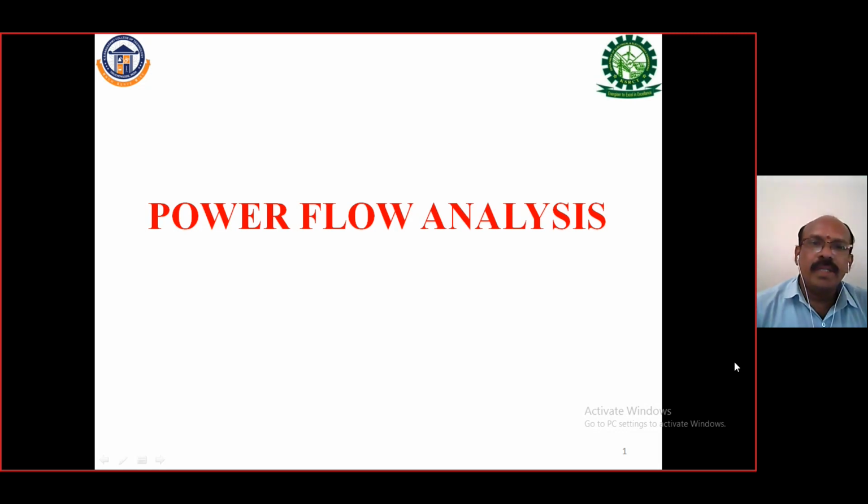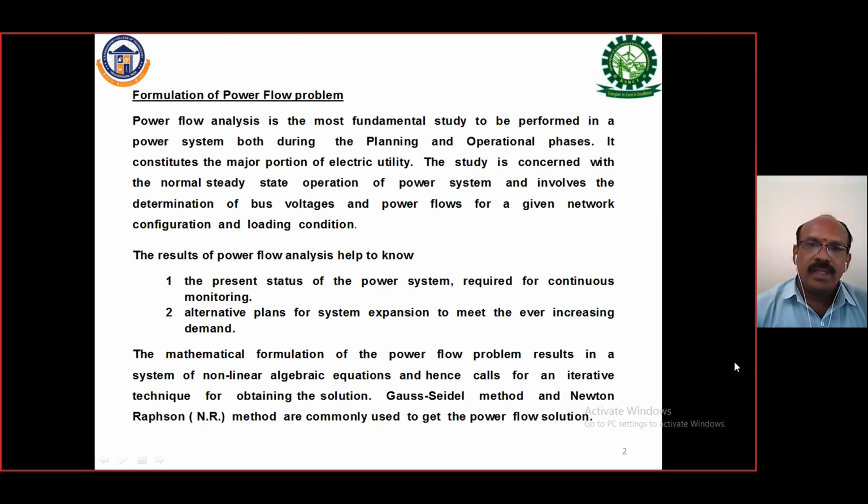Today I am going to take the class Power Flow Analysis. Actually, power flow analysis is the fundamental study. It is performed on the power system during the planning and operation phases. It constitutes a major portion of the electric utility. This study is concerned with normal steady state operation of the power system and involves the determination of bus voltage and power flows for the given network configuration under loading condition.